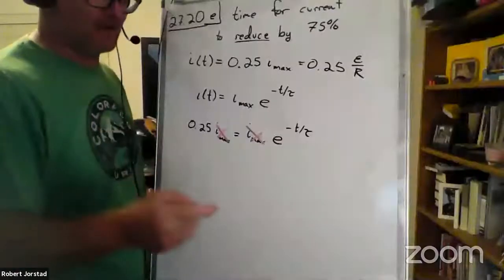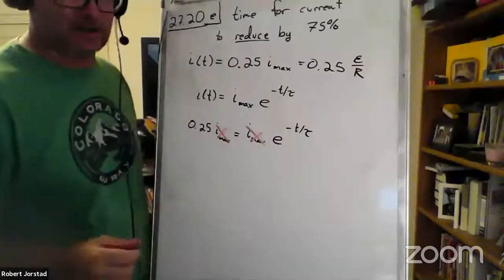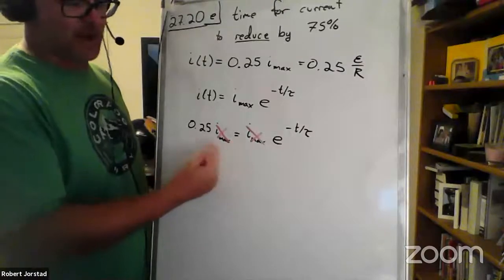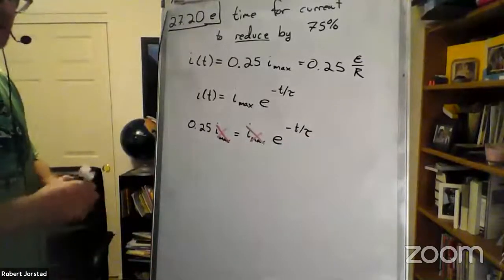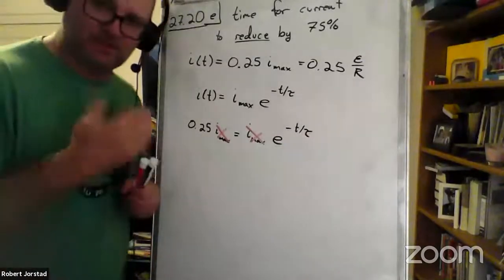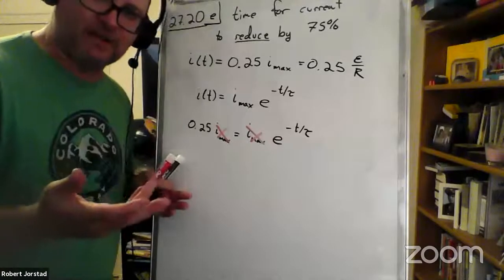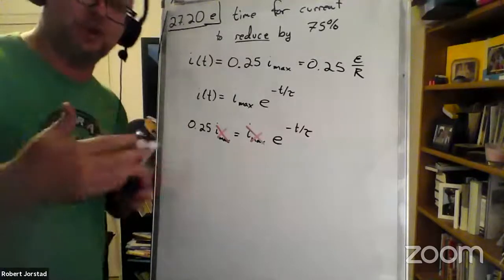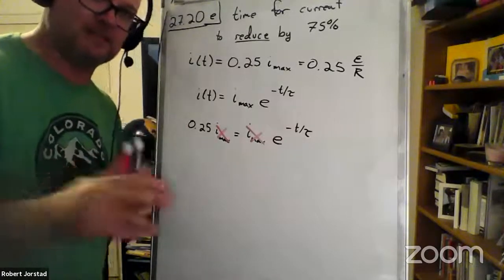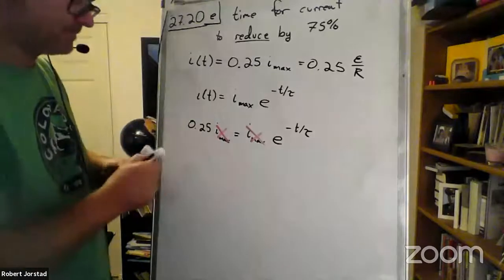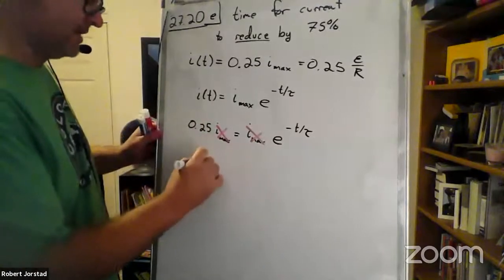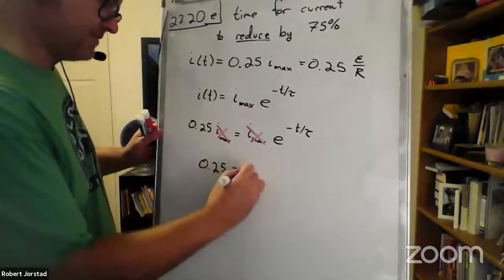Okay. Wouldn't resistance matter because it's in tau? Exactly. I was trying to lull you into it, and I couldn't trick you. Just because the battery voltage doesn't matter, resistance is still hidden inside tau. So absolutely. This would be true whether you used a 2-volt battery or a 6-volt battery. Now, obviously, that would affect the total amount of max current, right? But okay, whatever. So let's take a look at this one. Tell me what I do with this equation.